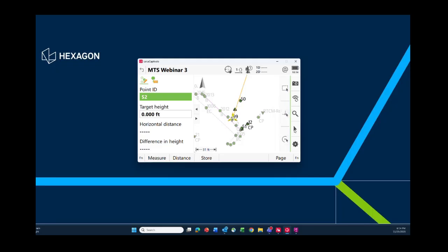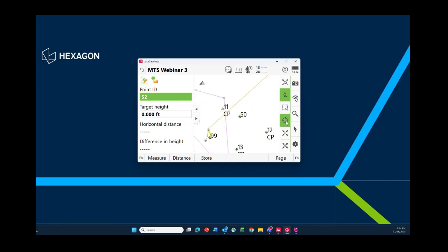And we have a tool here to do some selection. Those are quite useful if you work with background or reference files like DXF, IFC file, and you want to select a building corner from an IFC file or from a DXF. So you pick element from drawing and you can import them easily. And then 3D view, you can switch to 3D view. And then if I go to zoom, there's one more option to zoom, it's the orbit. So you can now zoom around in the 3D view and rotate. Sometimes that could be useful to do some point validation.